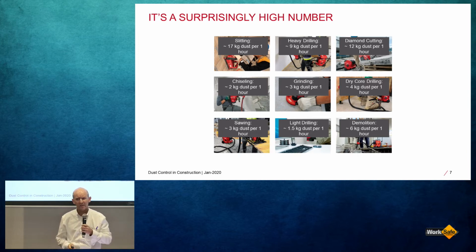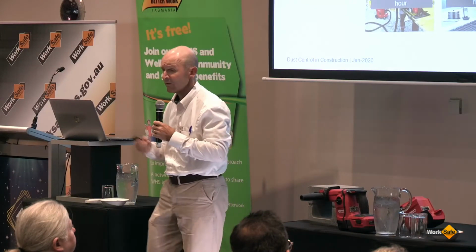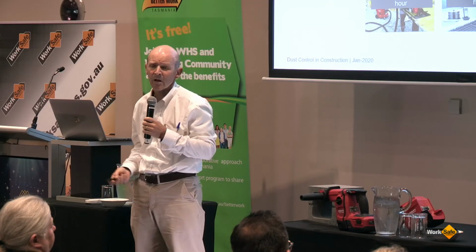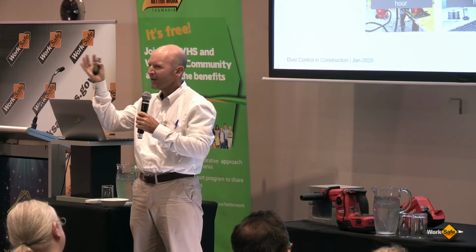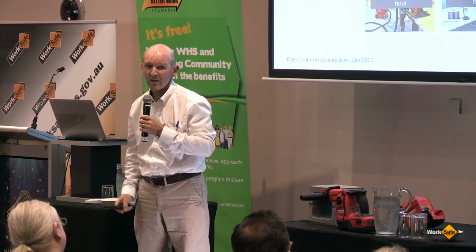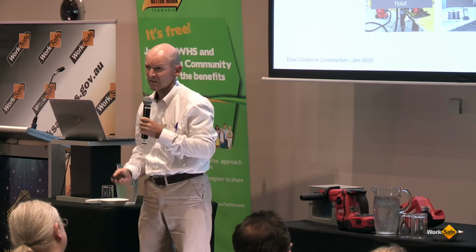Another watch-out is grinding, particularly in enclosed spaces. For example, you're cleaning up stairs in an enclosed stairwell. You're going to be generating yourself a cloud of dust to work in that's not going to settle out really quickly. That's something to watch out for.